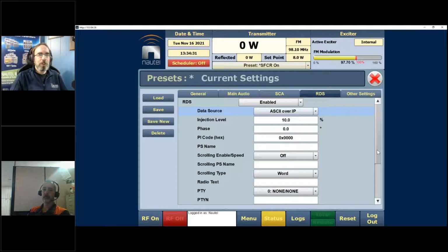On our system, and I showed a couple of screens from it earlier, we're running Playout 1 Pro, I believe, and we've got it configured to send the data once every cart change. So every time we fire a new spot, line, or song, it sends the data once only. One of the automation vendors did an update, and in the process, they set the default to send the RDS data every half a second, and it was just overwhelming the front end of the transmitter.